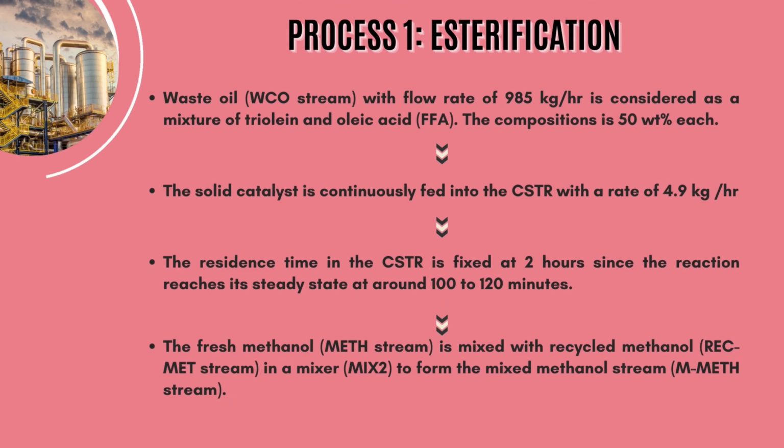In the first esterification process, the waste cooking oil stream with a flow rate of 985 kg per hour is considered as a mixture of triolein and oleic acid. The composition is 50 weight percent each. At the same time, the solid catalyst is continuously fed into the CSTR at a rate of 4.9 kg per hour. The residence time in the CSTR is fixed at 2 hours since the reaction reaches its steady state at around 100 to 120 minutes.